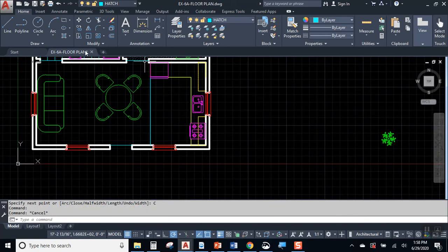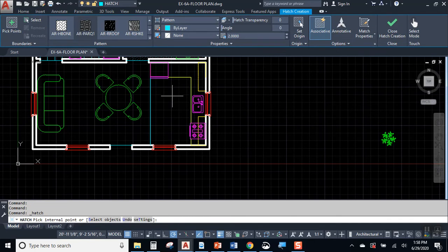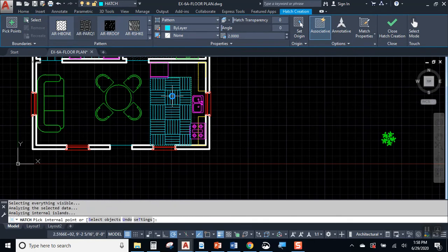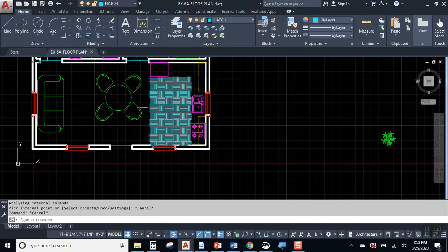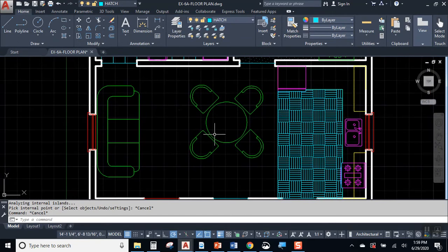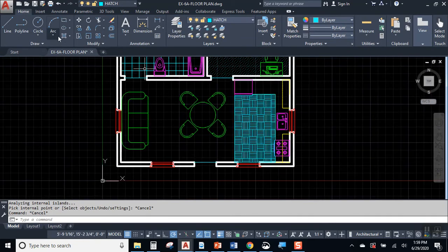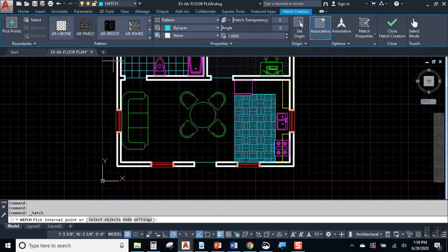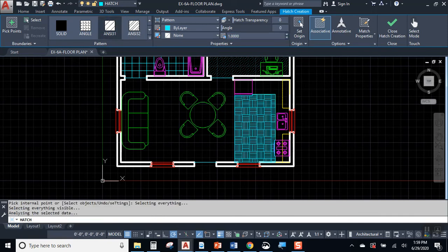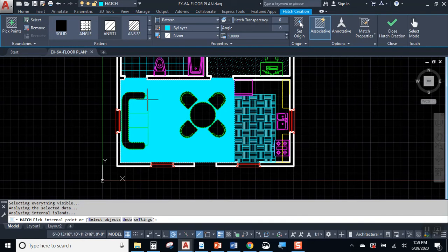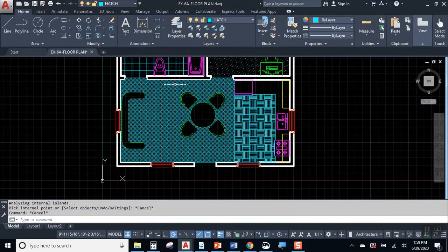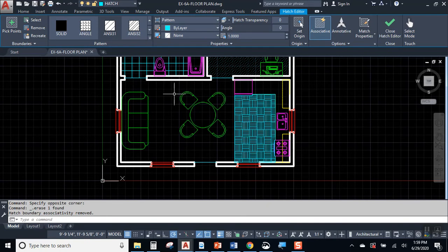Okay, so AutoCAD should have an easier time hatching that shape than trying to figure out, yeah, there we go, that's much better, right? And maybe reducing that down to 1. That looks good. And how about for our living room area? Maybe some hardwood flooring, some laminate flooring. I'll go up to ANSI 32, ANSI 31. And we'll do ANSI 31 in this area. You can see it's spilling into the couch though. Not really happy about that.